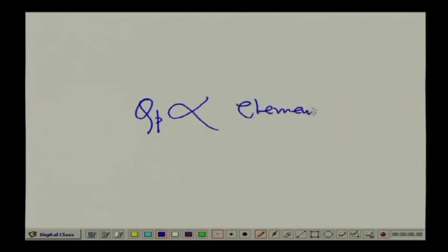I have to make element spread very high to make the QP high. This is very undesirable. That means I have used large capacitance ratios. That means if one capacitor is 1 picofarad, the other capacitor might be several thousand picofarad, which is not acceptable, or if one resistance is 1 kilo ohm, and the QP is high, the other resistance might be some mega ohm. So, that is not desirable, right.